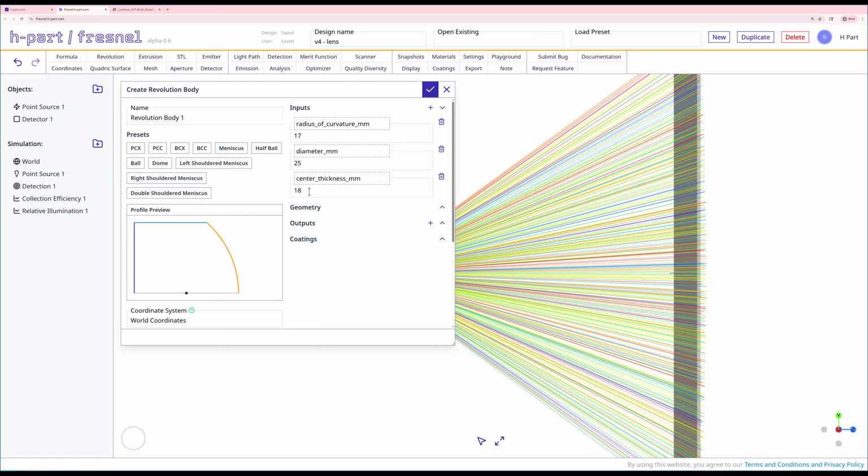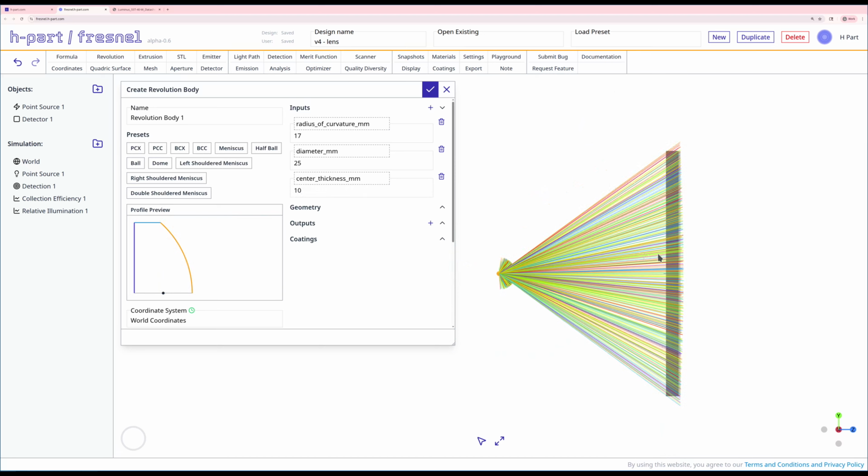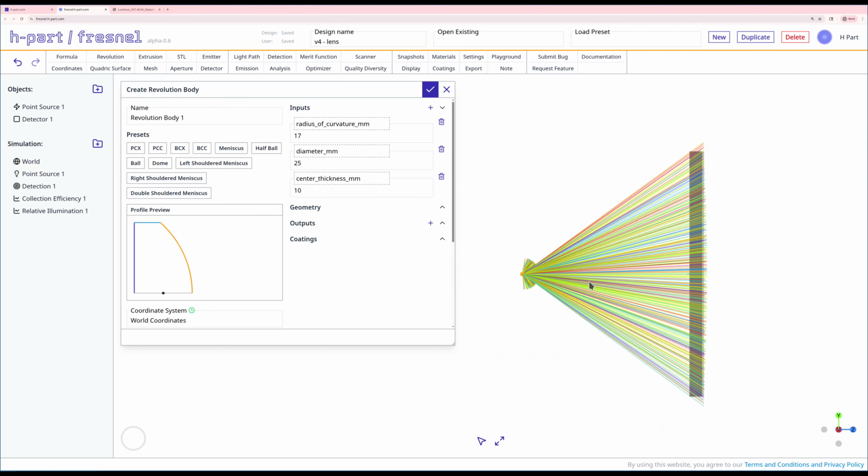Okay, so our goal with this flashlight is going to be to get most of the light in a 10-degree cone. So this is going to be not a narrow beam flashlight, but not a very broad beam like we currently have, where it's just throwing the light everywhere, so it'd be difficult to see anything. We're going to compromise. We're going to throw out the beam at about a 10-degree spread, and we're going to optimize the lens to do that.